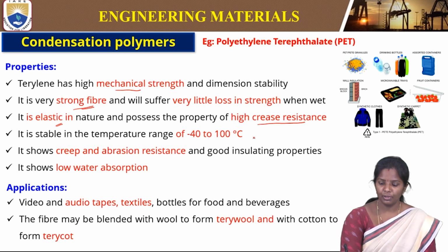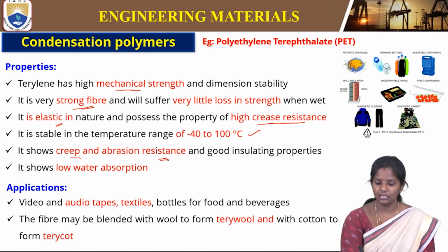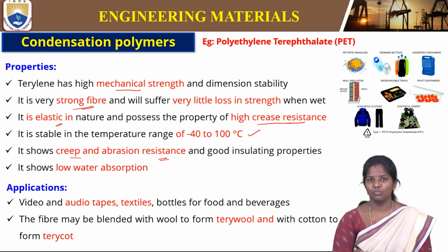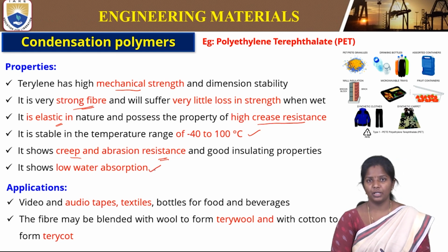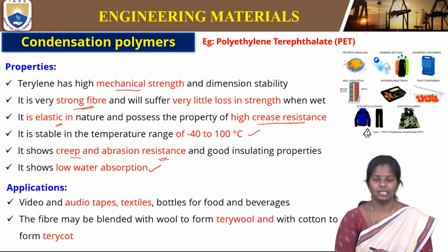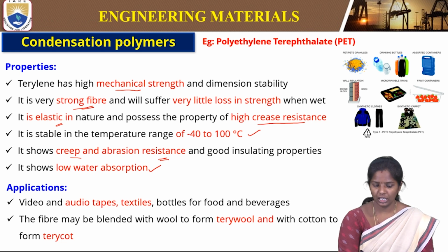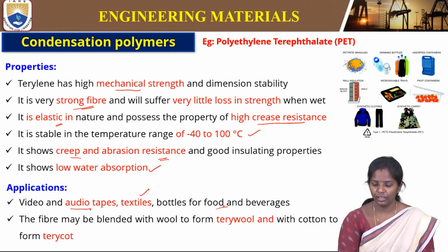So it is stable at temperatures of -40 to 100 degrees centigrade, and shows creep and abrasion resistance and good insulating properties. So most of the polymers are applied in all the insulating applications because of good insulating properties, and it also shows low water absorption. If you see our fabrics also, some fabrics like polyester absorb very less water, so the water drains easily. Therefore the applications are like video and audio tapes, textiles, bottles for food and beverage.